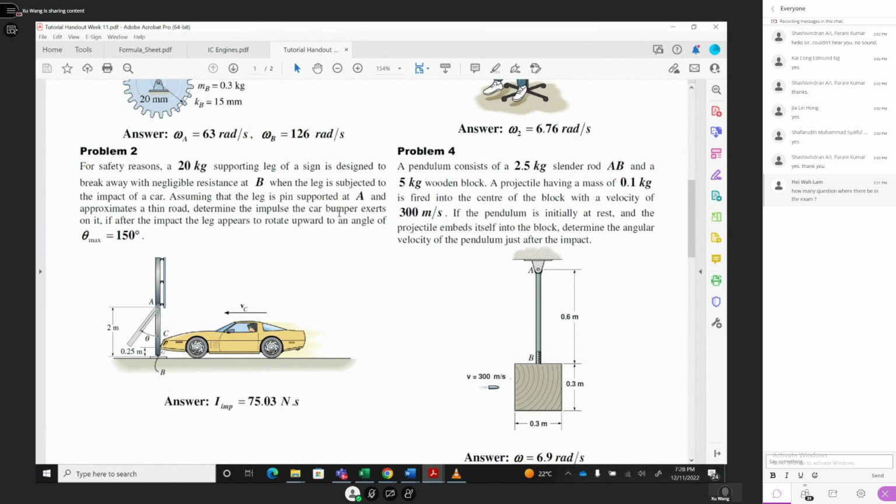From this I omega, we should know the rotational inertia is 1/3 of ml square times omega. Then from the moment times T equal to I omega, you can find what omega is. With this omega, you use energy conservation. For this position you have half of I omega square, which is the total rotational kinetic energy.